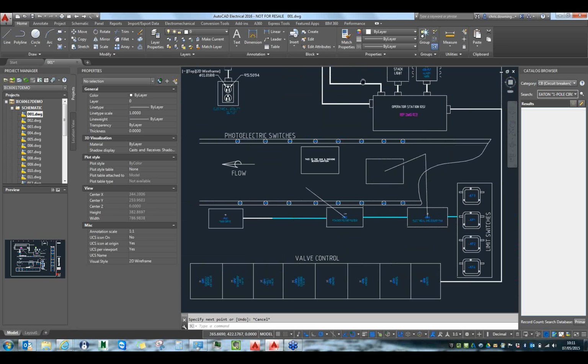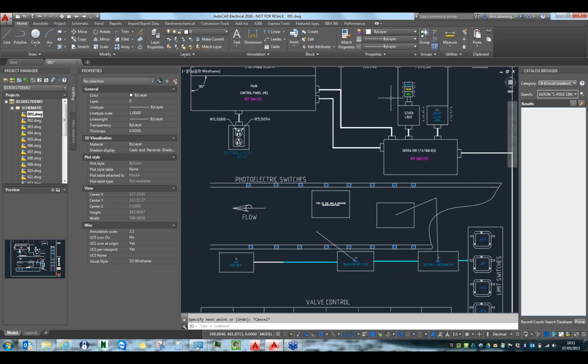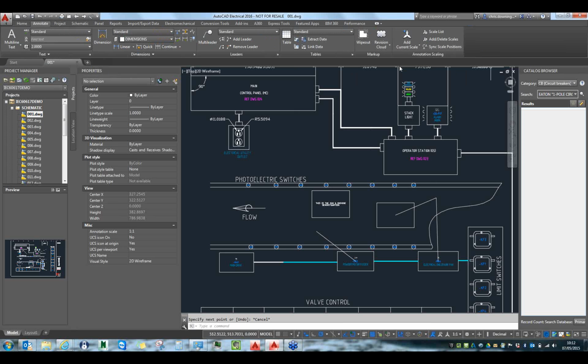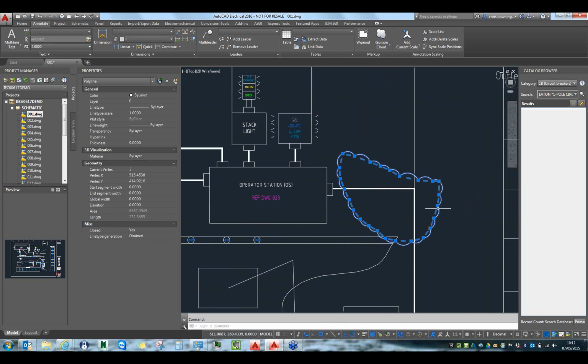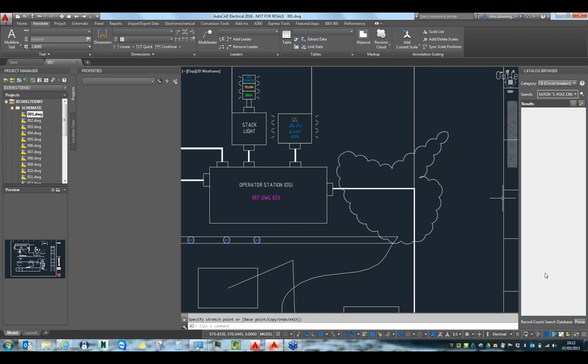And I'll come to the last new feature in plain AutoCAD, which is one of my favourite features personally, intuitive revision clouds. They now act as if they're a polygon. So we can select on the annotation tab revision cloud and we get three options. We've got freehand, which is the same as it used to be in 2015. A little bit fiddly, but okay. And with a bunch of arcs, you pull one grip and it will just pull that one grip and give you a weird shape.